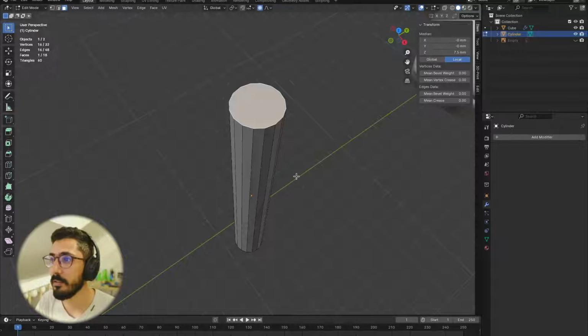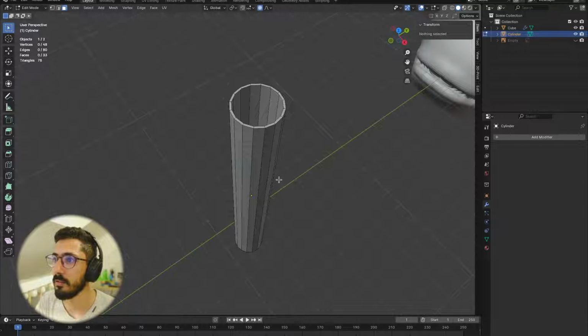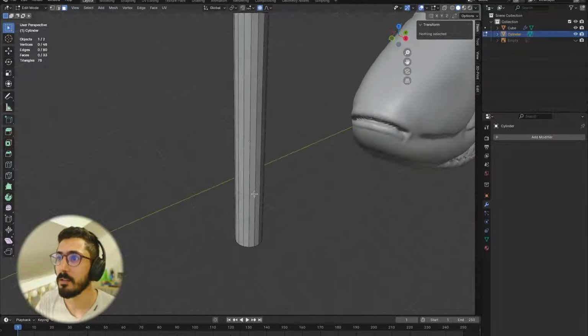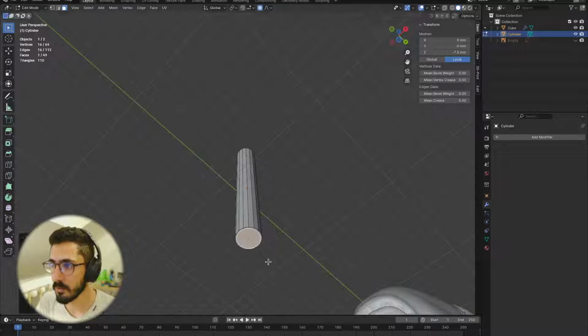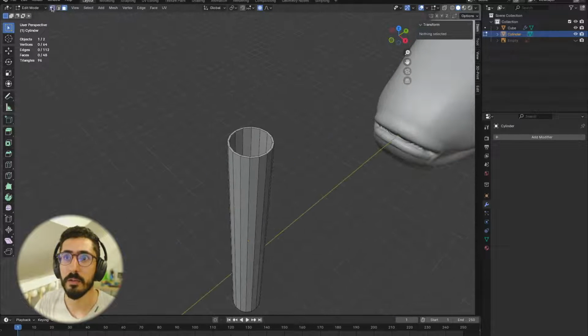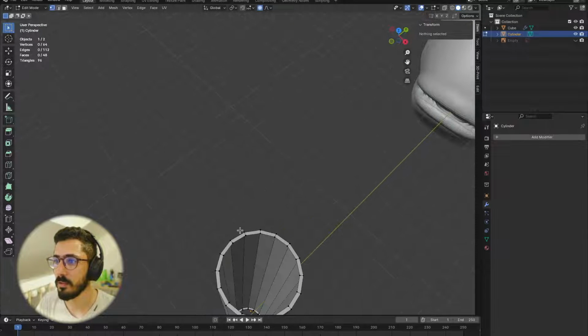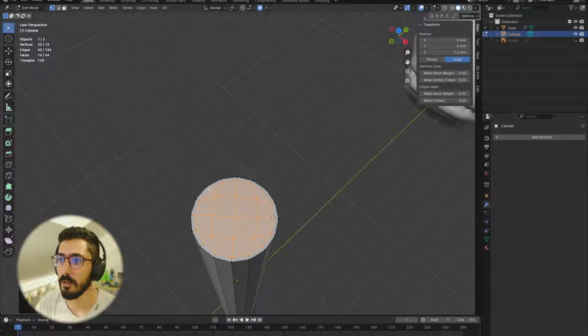First, I'm gonna inset the faces like that, and then I'm gonna delete the face. Gonna do the same down here, inset and delete face. And now if I go back to vertex, let's select this loop, double click to select it, face, grid fill.